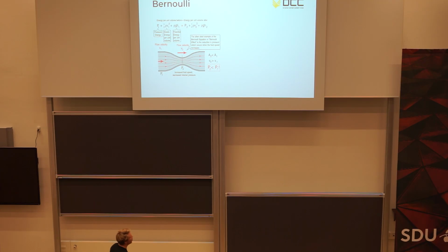It will drop the pressure actually, and you can use it for all kinds of reasons. Usually Venturis are used in carburetors to get gasoline to atomize in air. So if you imagine you have a little hole there which feeds gasoline, you could get the ongoing air to just atomize the gasoline and then burn that mixture. But yeah, it's basically that.